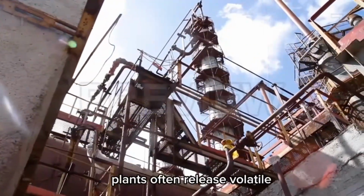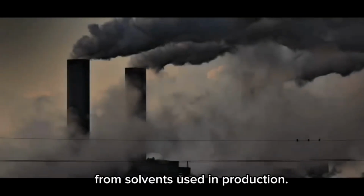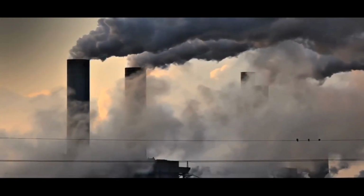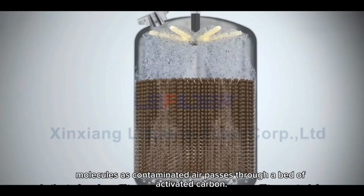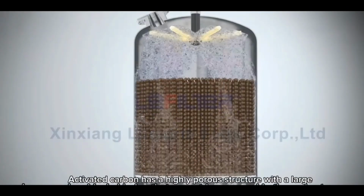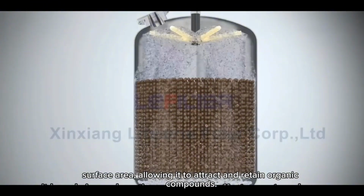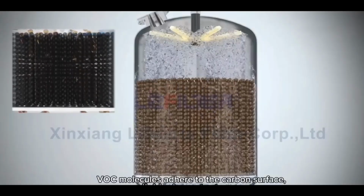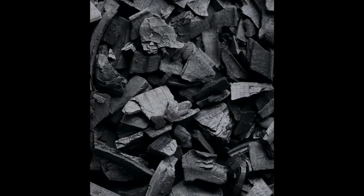Chemical manufacturing plants often release volatile organic compounds from solvent used in production. One effective method to control this emission is activated carbon adsorption. Activated carbon adsorption works by capturing VOC molecules as contaminated air passes through a bed of activated carbon. Activated carbon has a highly porous structure with a large surface area, allowing it to attract and retain organic compounds. As polluted air flows through the filter, VOC molecules adhere to the carbon surface while clean air is safely released back into the environment.